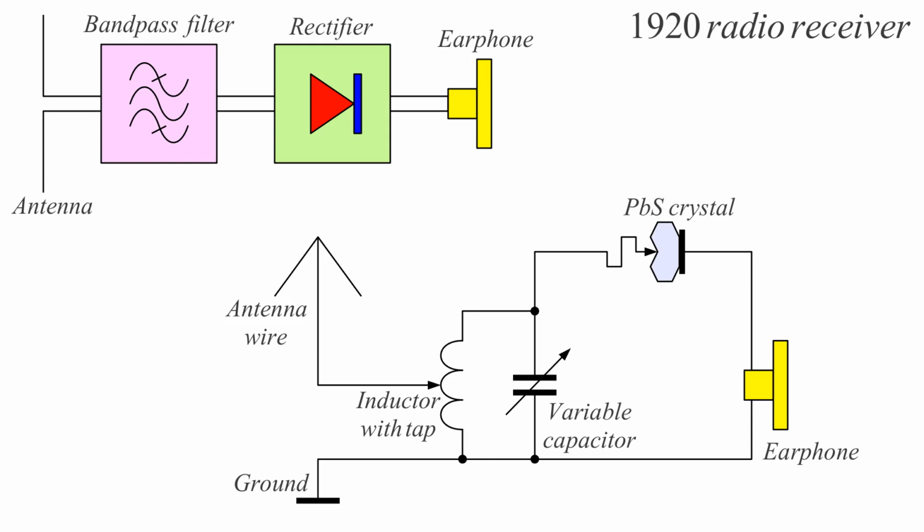So what were the first radio receivers? The first radio receivers had a band pass filter on the antenna. Also the antenna worked as a part of the band pass filter, and a rectifier that converted RF signals into audible low frequency signals in an earphone. So this was the simplest requirement for this receiver. The antenna was usually connected to a tuned circuit, an inductor and a variable capacitor to adjust the frequency of this device, maybe also a variable inductor with an adjustable tap to match the impedance of the antenna, and a crystal.